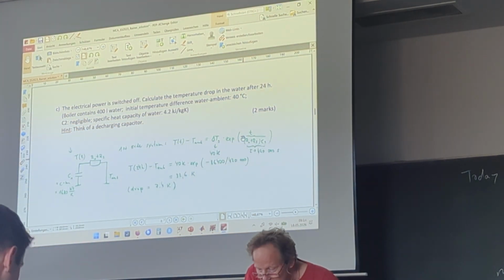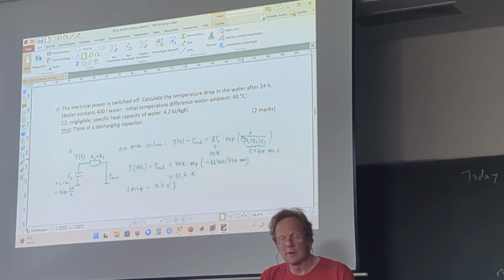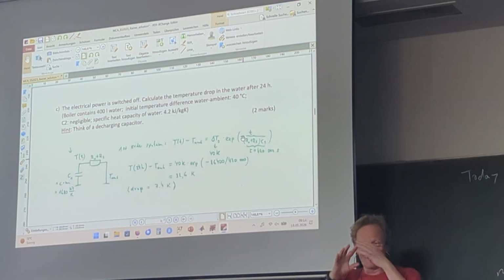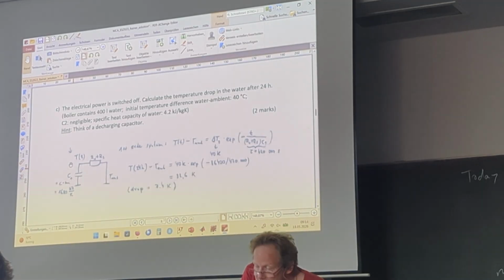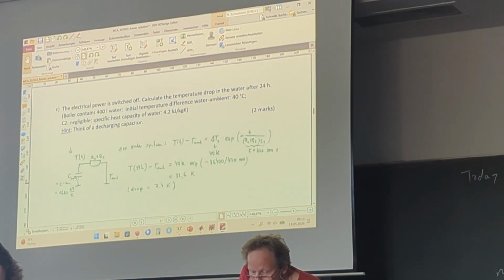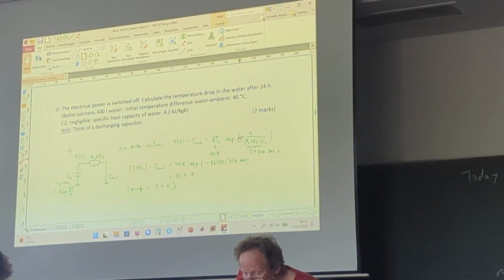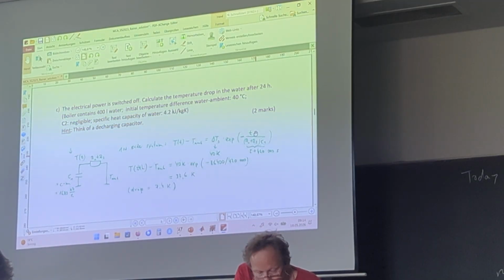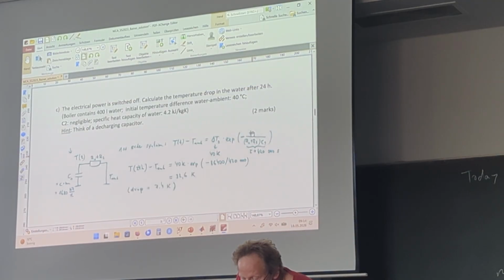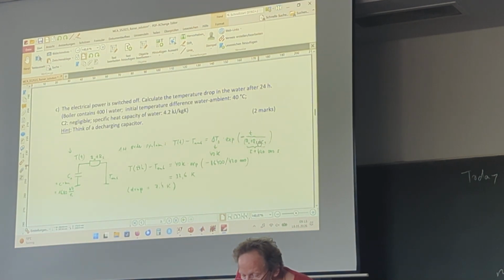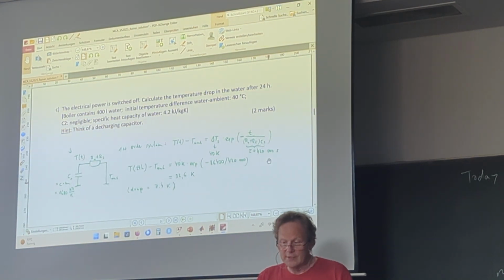Whenever we have a constant with a certain change, but then we have constant inputs, as a first order system, and a capacitor is one such, we get exponential curves. Okay, so it depends on time, and time is divided here by the time constant. We used that a couple of times. R multiplied with C is a time constant.